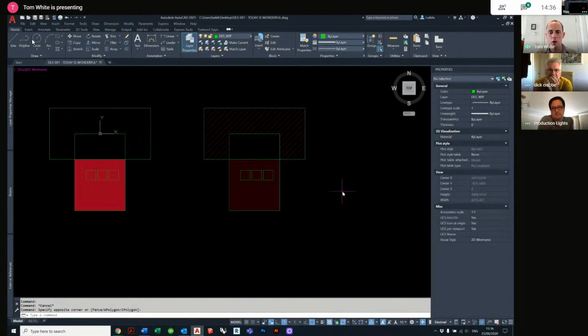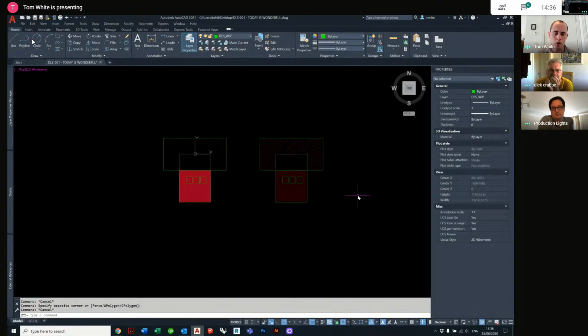But a very nice command that I think there's two different commands that do the same thing is hatch to back. So it will send all hatches to back, and I think also there's text to back. I'm sorry, yeah, text to front. Sorry, that would make sense, wouldn't it? Yeah, text to front. So hatch to back and then text to front are really useful tools.